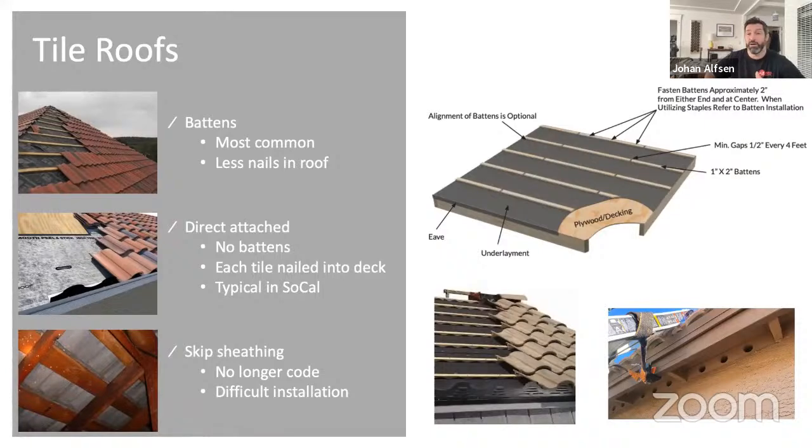Or maybe there's an upgrade where you have plywood and then you have skip sheeting underneath, and you might be hitting those skip sheeting boards instead of the rafters, and it might trick you into thinking you're hitting the structure of that. So it's just good to know what you're getting yourself into. A lot of installers don't like getting in the attic, but that is the best way to tell what's going on, or making sure you're making positive connections to the rafters.